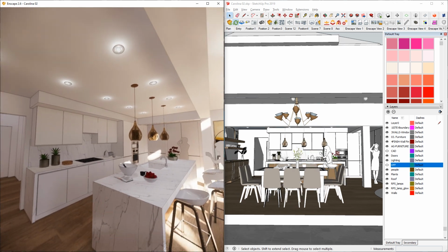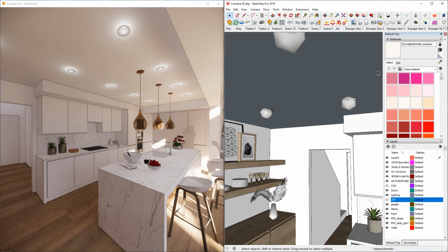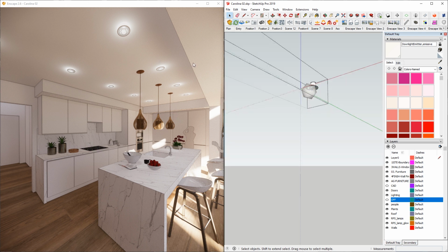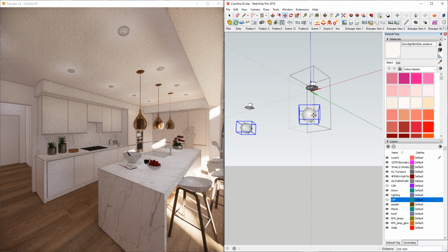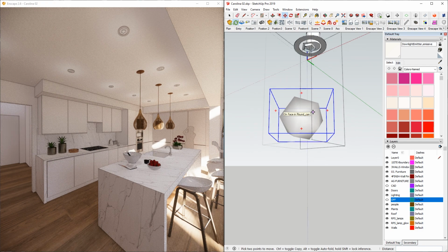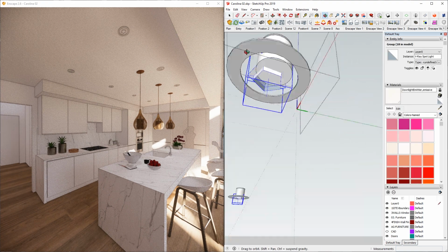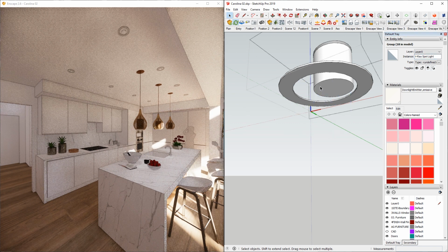So let me just look at that scene here. So I can immediately see there's something going on that is an emissive material. I just color sampled it by holding down the Alt key on the paint bucket tool. And then that is causing this sort of weird light effect. Let me double click that and then move that down a bit. So that is causing that sort of light bleeding effect. I don't think this is the right workflow, so I'm just gonna get rid of that one. This is looking like a V-Ray light. Yep, so V-Ray spotlight, we don't need that anymore.